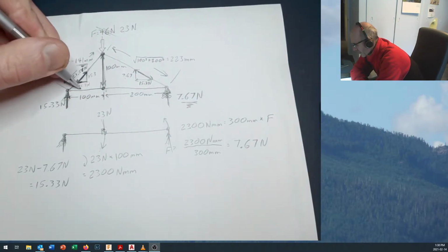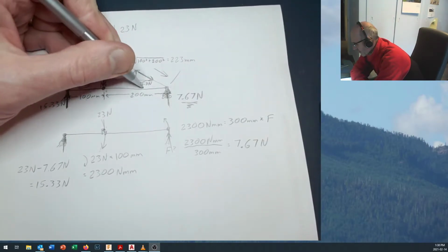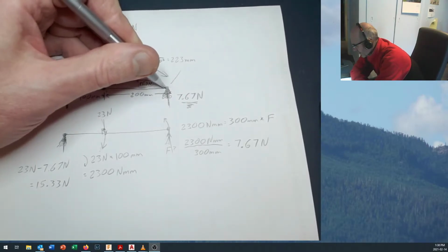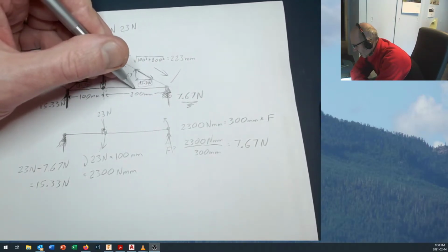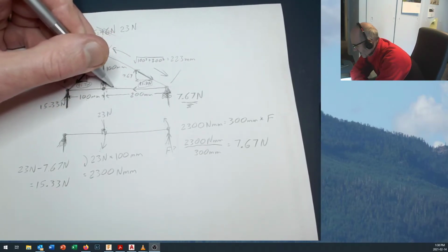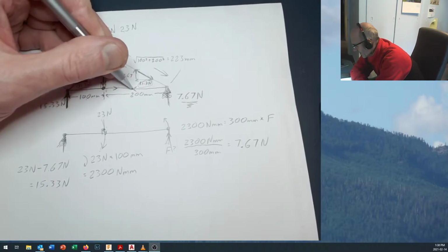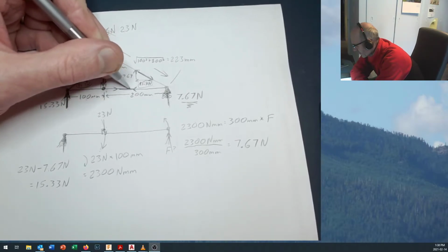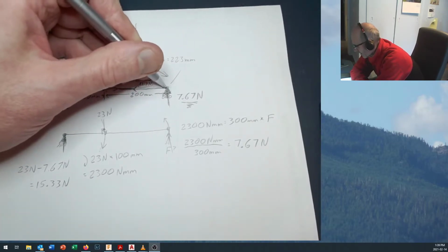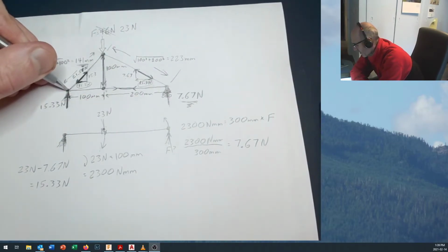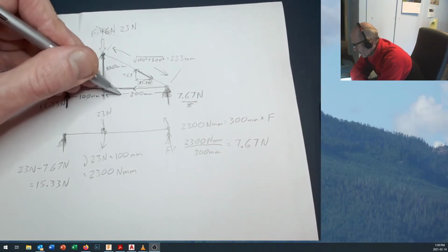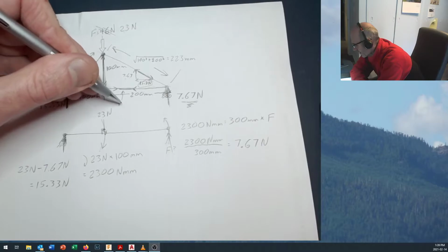because this force right here and this force right here have to balance out, because right in here, this one is pulling out this way, okay? And so this member right here is pulling in on those two nodes. It's pulling this one in this way with 15.3, and as it pulls that one in at 15.3, it's also pulling that one in at 15.3. So we've got 15.3 newtons in tension in the bottom.